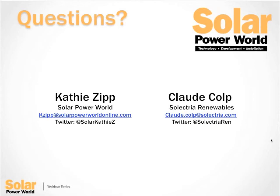Now, I keep on talking about nuisance tripping, but it's very important for people to fully understand that every time there is a contactor that opens and closes in an inverter or other externalities in the power distribution system, that creates noise in the line. And we already discussed that noise is the signature that we look for in order to identify an arc. So if we have other things operating inside of an inverter that are creating those noises that resemble an arc, then we're going to have a lot of problems.